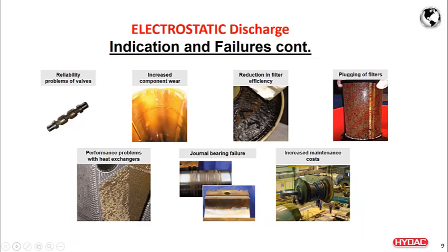Again, if you have more reliability issues in the valves, valves getting stuck open or stuck closed because of the varnish, and varnish catches the contaminant and causes the stuck open or stuck closed valves. Then more component wear, reduction in the efficiency of the filter element because of the very high localized temperature causing the burn marks in the element.